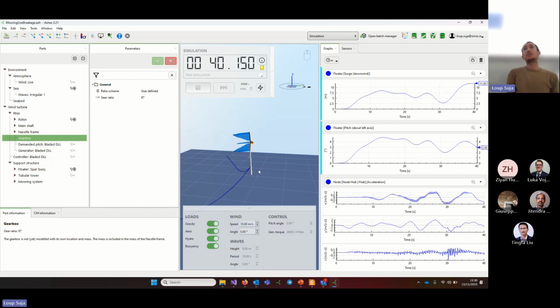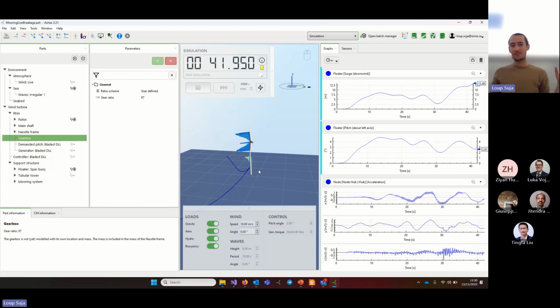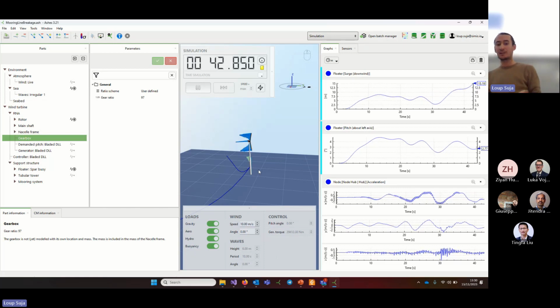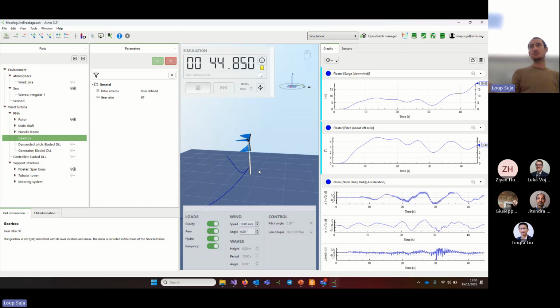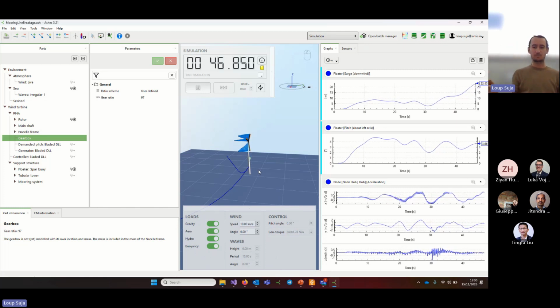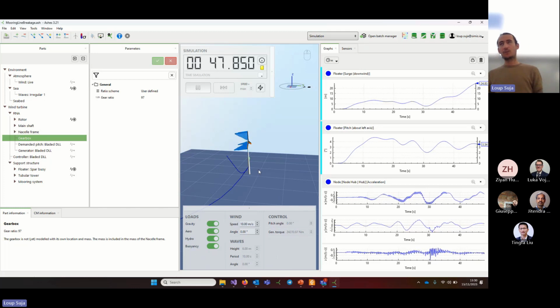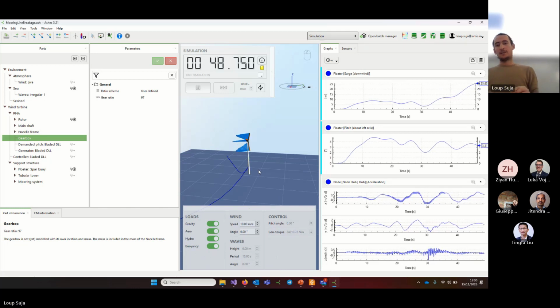This is very interesting because it allows you to say, okay, my wind turbine is not being held anymore by the mooring lines. Shut it down, and then you would enter the same procedure that we saw before, where you start pitching the blades just to stop the wind turbine from spinning.